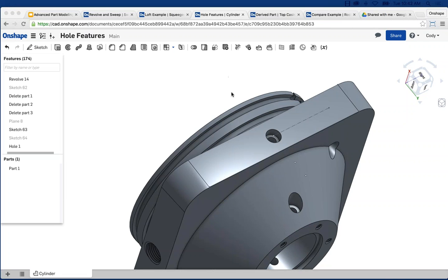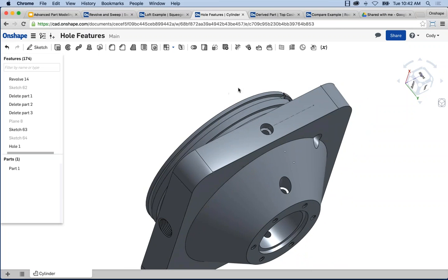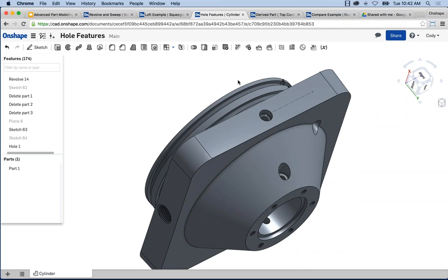And again, oftentimes, that level of detail in the 3D model isn't used, and it's simply called out in a 2D drawing. But if you want to go to that level of detail, you could certainly actually add the helix, draw in a triangle, and do a thread cut.